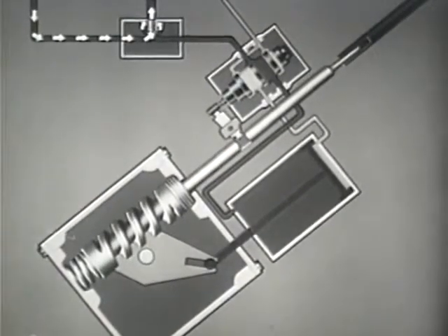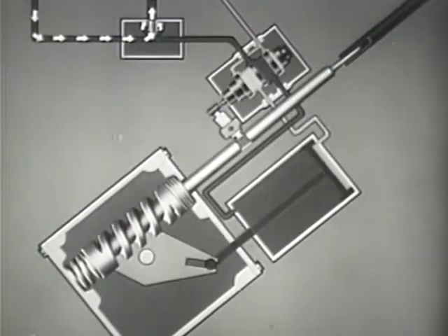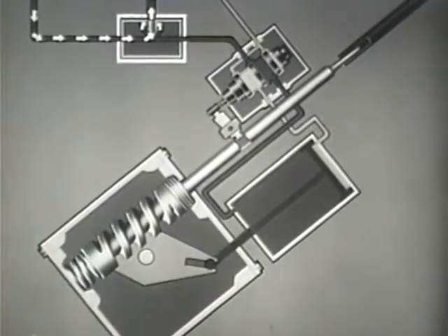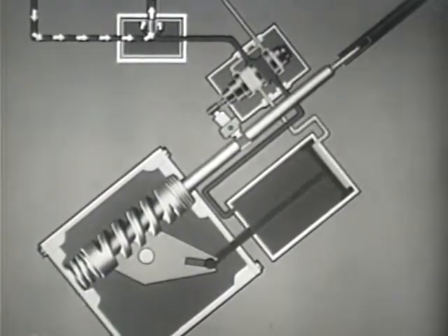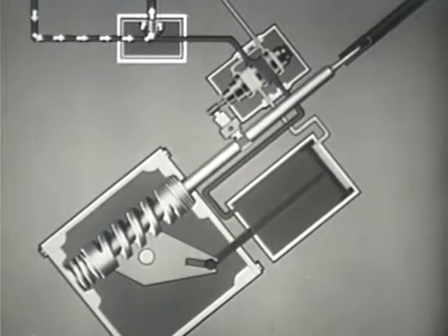When the piston reaches the end of travel in the power cylinder, the pump continues to deliver fluid, causing an increase in operating pressure. The relief valve provides an escape for this excess pressure back to the reservoir.